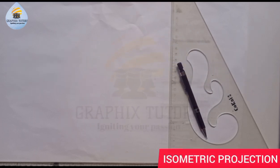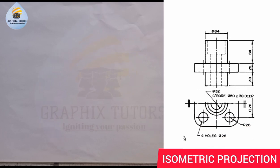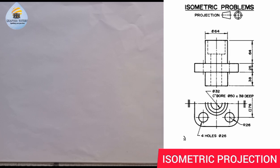If you look at the right hand side of the screen, you see two given views of a figure in first angle projection. Now we're told to draw the isometric view of these two views. How did I know they're in first angle? Because of this symbol you see at the top of the figure. It shows the first angle, meaning that this is the front elevation and this is the plan.